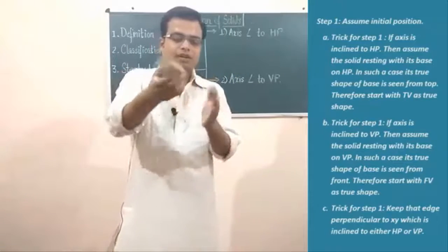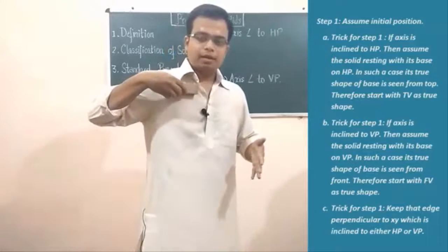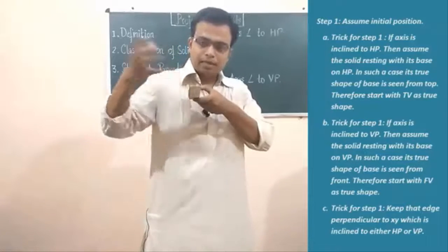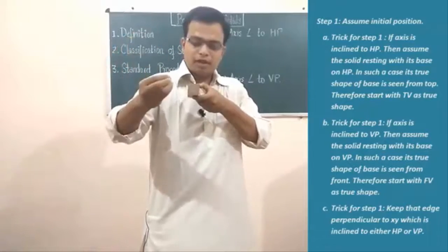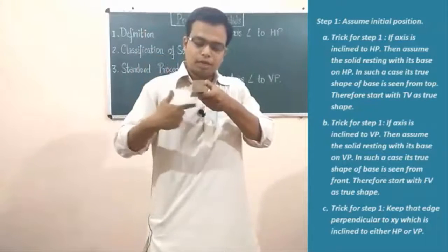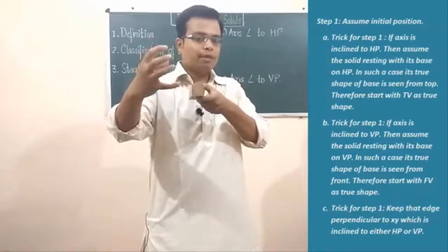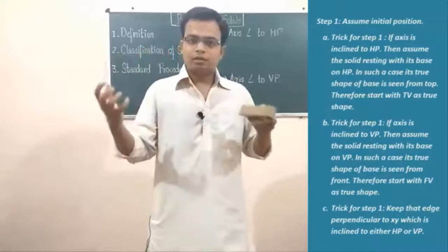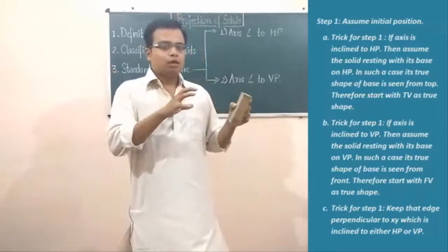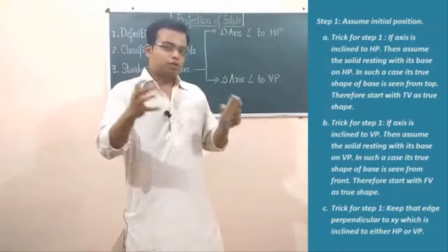If the face is resting on the vertical plane, you need to keep it standing on VP. And then again, you have to ask yourself from where you can see the true shape of this face, obviously from the front, and therefore you have to begin by making the front view first. So that's exactly how you need to approach problems based on projection of solids.